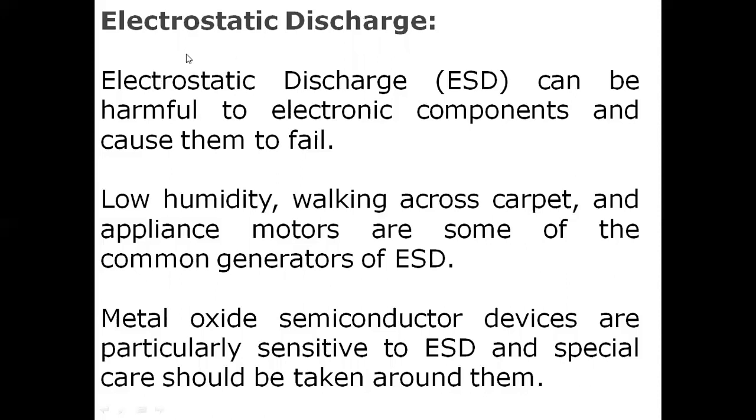So we'll see electrostatic discharge. We already have seen a little bit about electrostatic discharge, right? Electrostatic discharge can be harmful to electronic components and cause them to fail. We have already studied that whenever we are cleaning internal components inside the CPU, the electronic components of a computer, we should always use a soft cloth, an anti-electrostatic brush, or an anti-electrostatic vacuum cleaner, right?